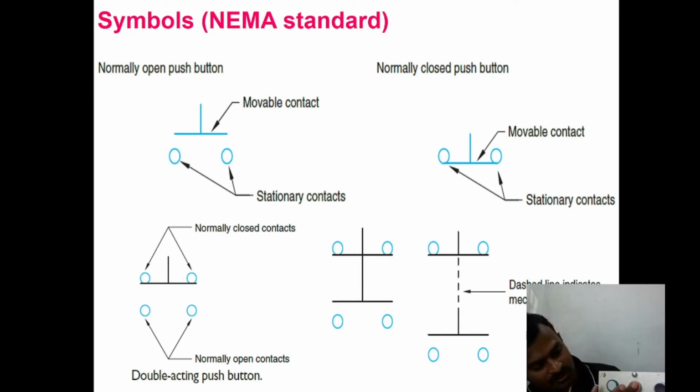Similarly, this one is used to turn off the machine. Usually we will use a NC contact or NC switch here. In case you need NO of this same switch for interlocking purposes or something like that, we can use the NO type here. Here we have two NCs, so if you have a double break, you can use these two NC switches. And similarly, here we have a black color one, so we can use either NC or NO type switches of this.